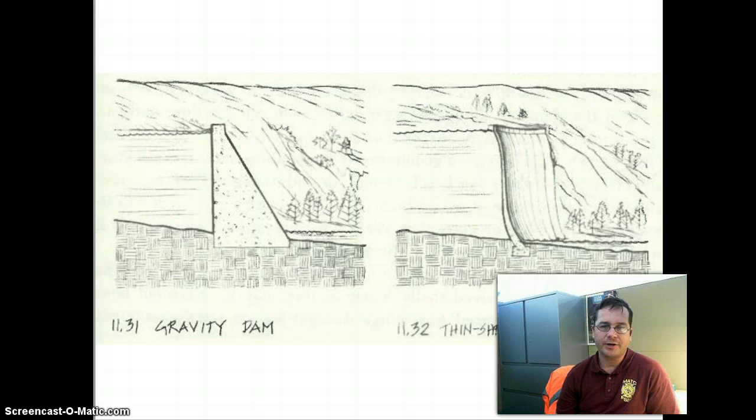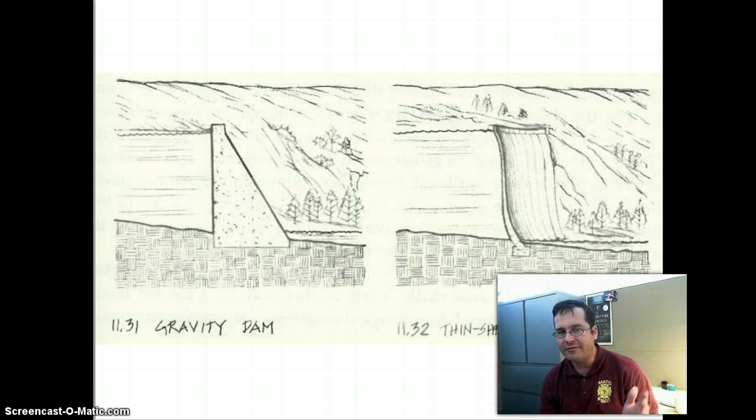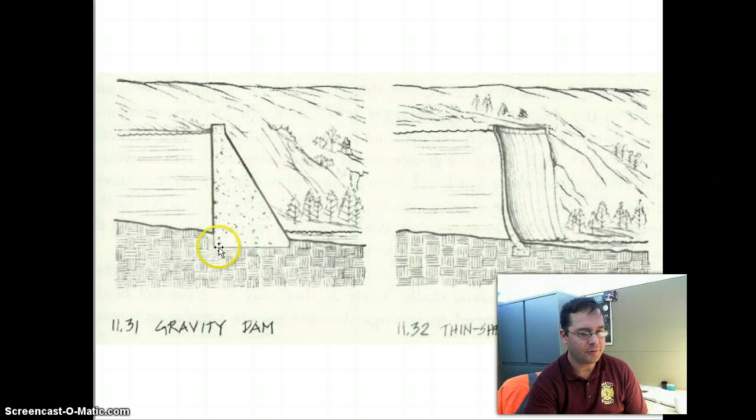Complex shapes go beyond roof structures, and here's an example from civil engineering. The dam on the left is a typical gravity dam. This is the garden variety dam. You can go all over Wisconsin and see this type of thing. And essentially the way this thing works is it's just sufficiently heavy that an adequate amount of friction is developed with the soil to keep this dam from sliding with the weight of the water.